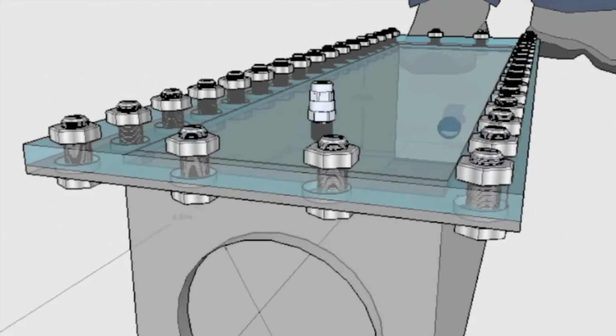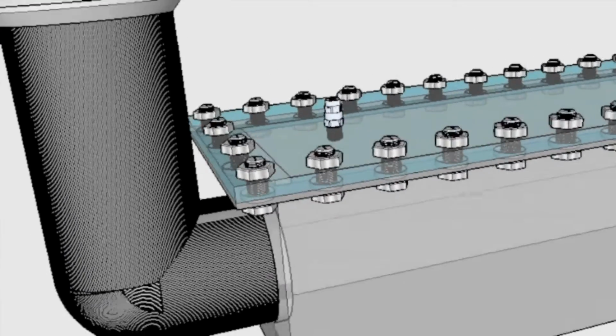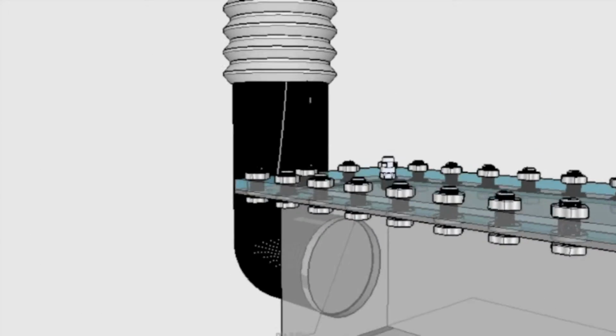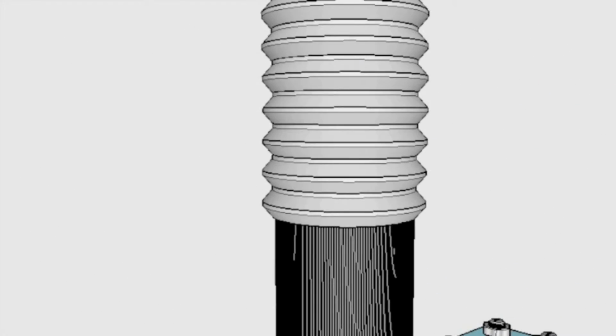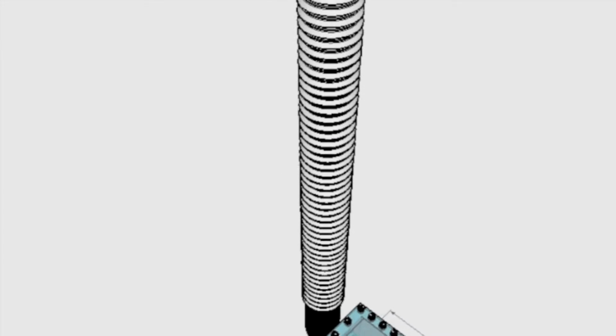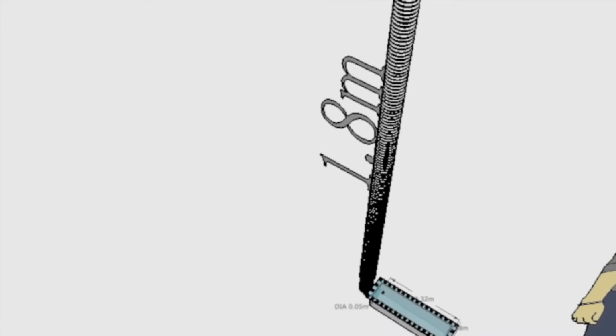To deliver the water, we had a 1.8 meter long tube to make water flow into the sample, also designed to handle a hydraulic gradient of 5 which is fixed in this study.